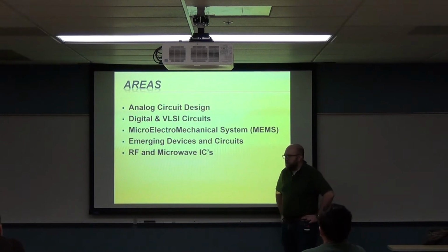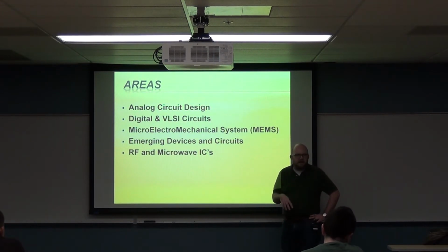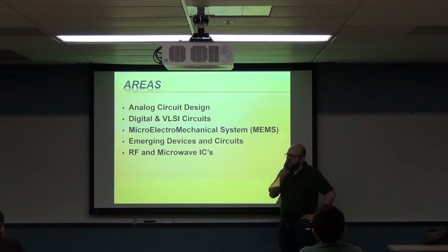So if you think about the time delays you might have been talking about for transistors, you might have been talking at rates of microseconds, or if any of you have built op amps and a low pass filter, it may have been filtering everything below 10 megahertz at the most, probably sub-megahertz, because it's really hard to get those things working. So those are relatively slow speeds. And then when I think about the slews in my high-end circuits, I have edges in my design that are 5 picoseconds. So I think that's on the order of 10, 20 gigahertz.